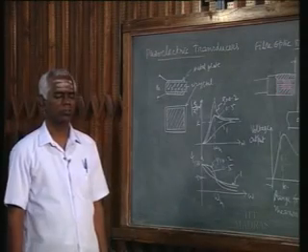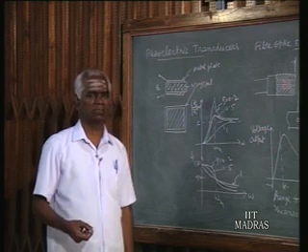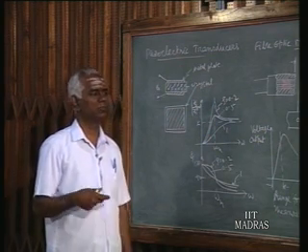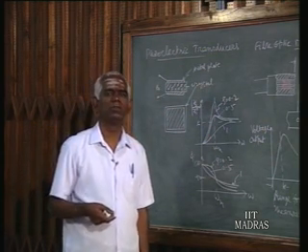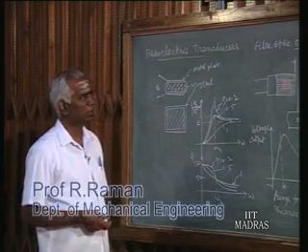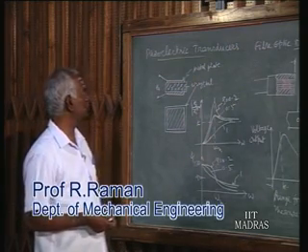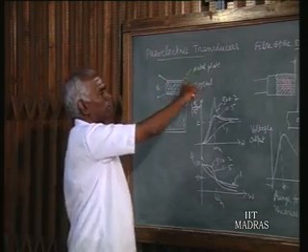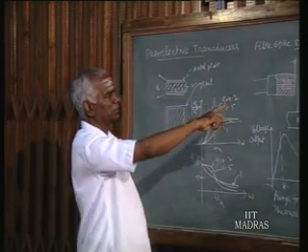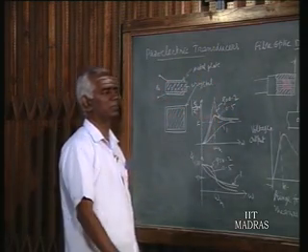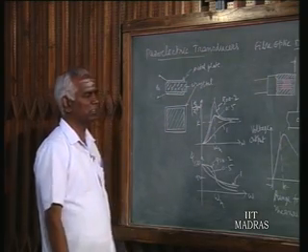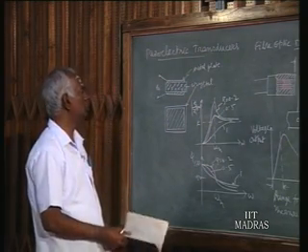Apart from the transducers using resistance, inductance, and capacitance, we have some more transducers for measurement of displacement. I am bringing under that three different transducers: piezoelectric transducer, fiber optic displacement transducer, and seismic absolute displacement transducer. Of the various types, these three are widely used.